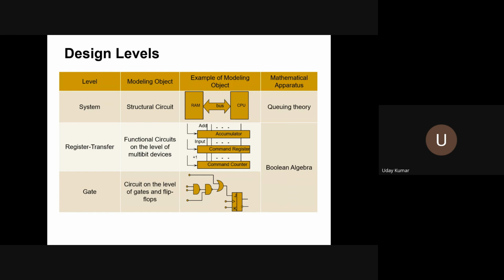So imagine 4 gigabit per millimeter square is the memory density. In 1 centimeter square, how much memory can you embed? These are all the aspects that come while the architect is deciding the spec of the chip, the memory, and the bus width.